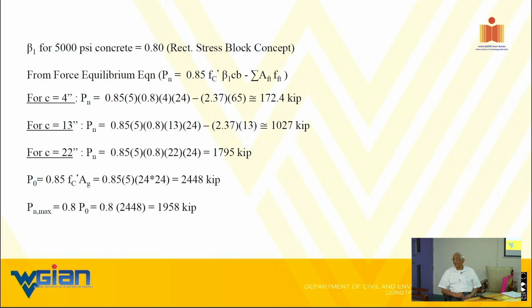We convert it to cylinder strength. Then we multiply the factor, which is 0.85. From there it is coming to 0.85, and then we divide by the material safety factor of 1.5, so it comes to 0.447. For columns, again we reduce for the accidental eccentricity. That's a lot of penalty.